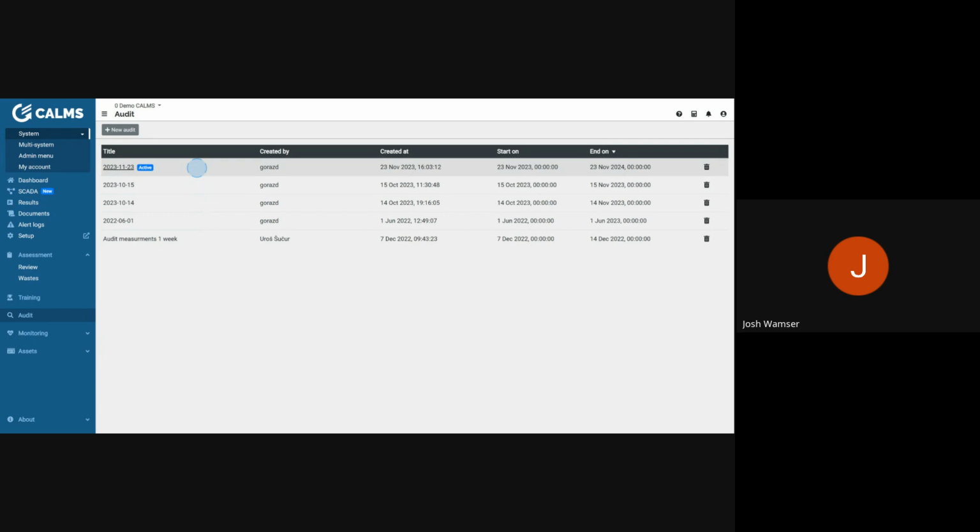But with the data that you provided, we could have sat down with that customer and said, hey, last year you spent directly on electricity 623,000, while the load profile showed you spent 592,000 on power when load compressor time was only 527,000 euros. So we have 65,000 euros savings just in controls without making any pressure or leak changes. So our conversation of getting a new compressor is moot just based on putting in proper controls. In fact, Mr. Customer, I'll sell you right now $65,000 of CALMS and just go ahead and start doing it permanently.